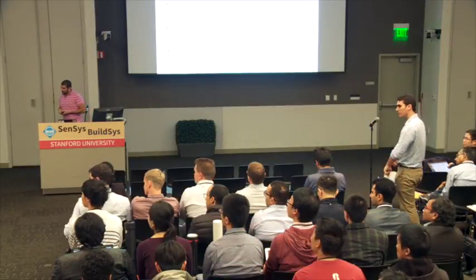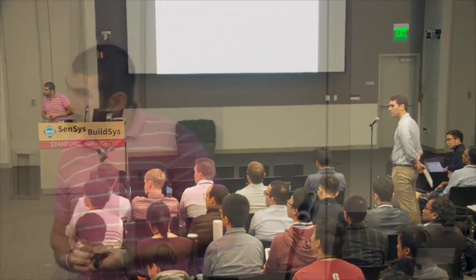Fair enough. And then the second part is, in your tests, if you can't trust the pseudorandom number generator, why not just mix the entropy, which is generally how people cope with entropy sources that are probably random but a bit suspicious? Oh, this is a good question. So you're saying something like you could build the secret key in, just flash it into the device, and then you're done. Yeah. It's true. That's honestly, for some applications, probably a perfectly reasonable approach, right? And yeah, if I build in a 256-bit key, I should be able to use that thing essentially forever. So yeah, why not just put it on flash and call it done?